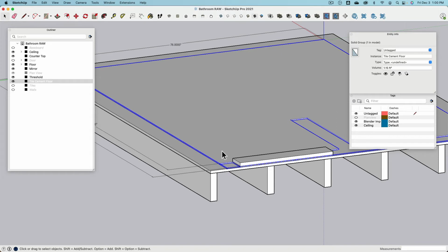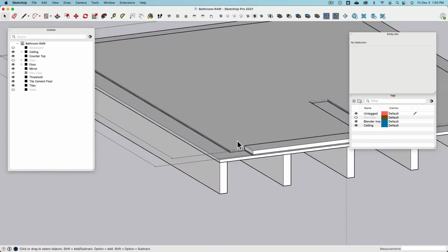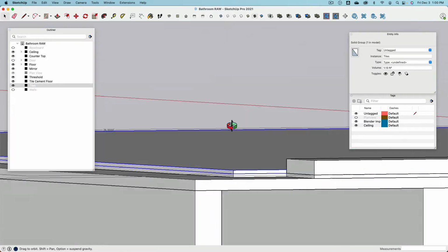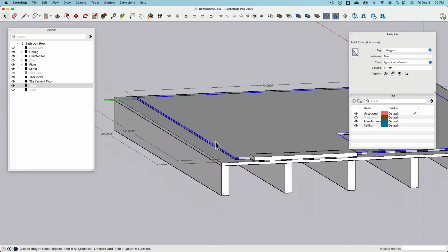So onto this surface, I took a dimension. What I found is basically for the cement boards, 1/4 of an inch or 1/2 an inch, whatever it is, that's then what we model. Onto that, I put down another geometry that represents the tiles. Onto the top surface of the tiles is where later I will put down the texture. But this whole object represents the vertical thickness, the material thickness, the volume of the tiles.